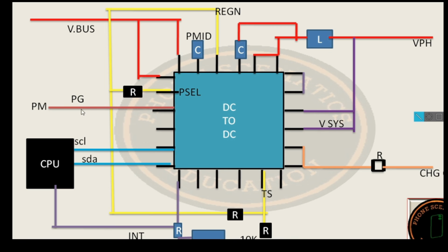After the charger is connected, the power IC generates our secondary lines, like buck lines and LDO lines, because when your phone is switched off, the power IC is not active. When you connect the charger, through this line the power IC boots and generates secondary lines, buck lines and LDO lines. After this, your power IC, through the CPU, generates the charging symbol on your display.